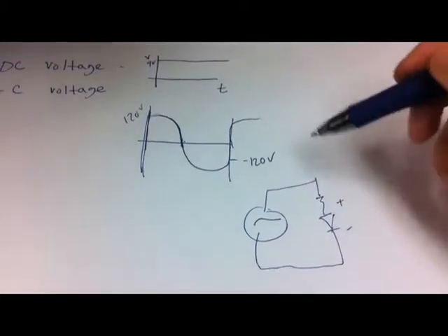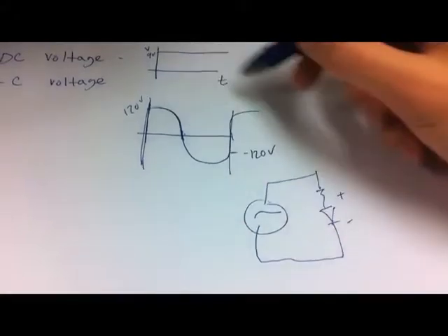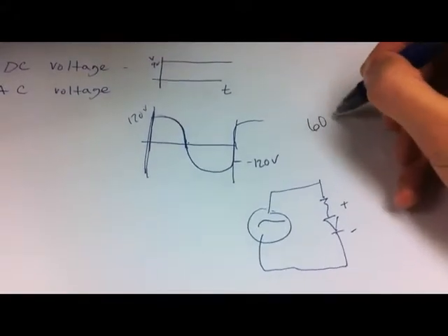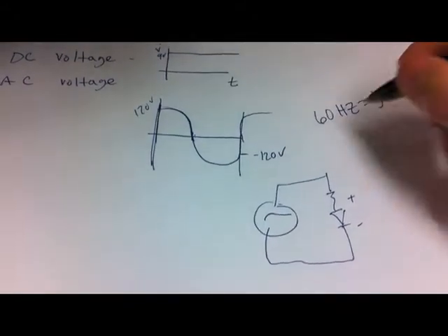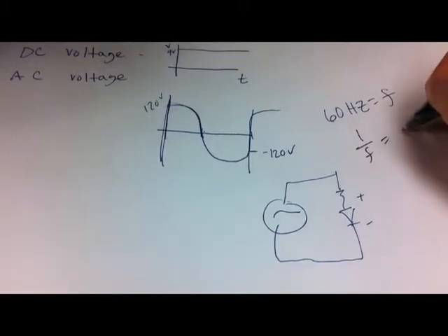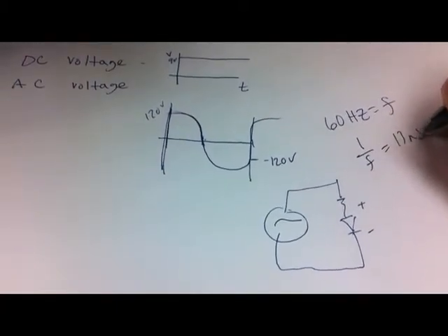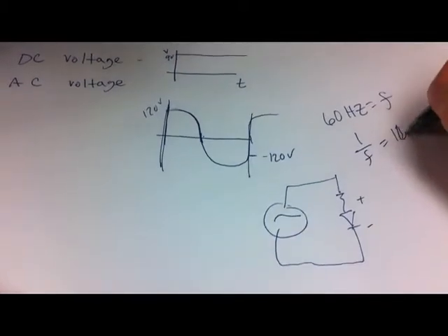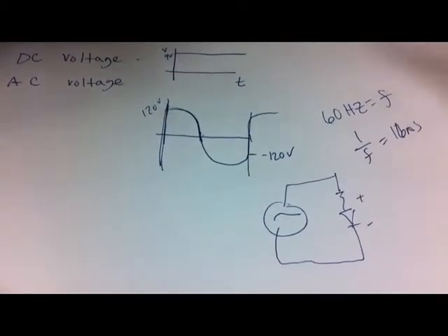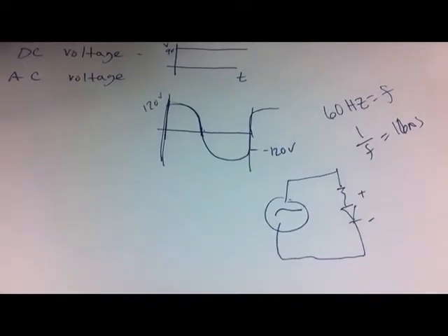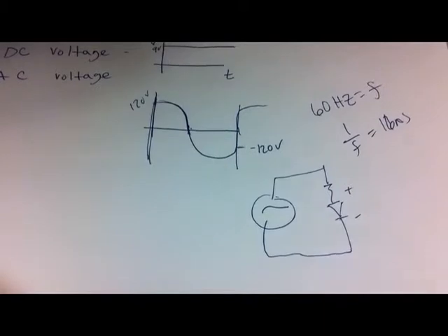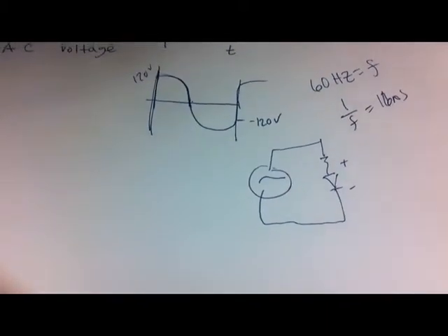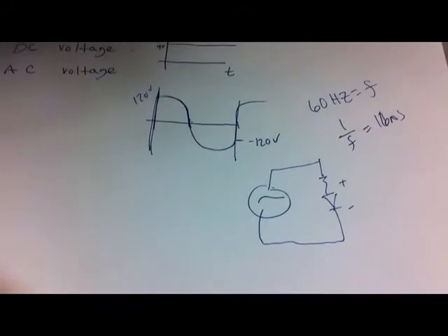It'll just be blank. Now, depending on the frequency of our source, which normally is around 60 hertz, one period will be 1 over frequency, which is roughly 16 milliseconds. Then that means that half the time, 8 milliseconds, it'll be on, half the time it'll be off. So it's going to flash. It won't be extremely apparent at 60 hertz, but you'll be able to notice it. However, it's very inefficient because half the time it's on, half the time it's off.